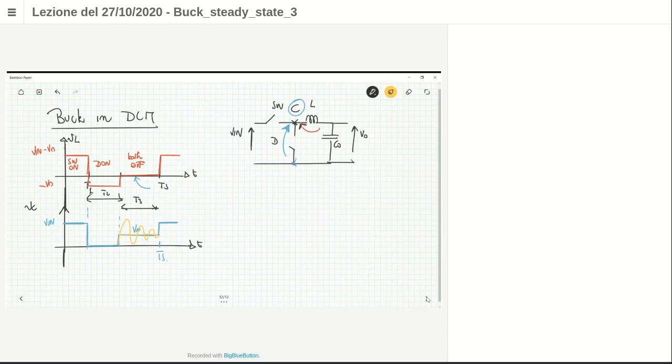For example, I just discussed with you the fact that inductors have a parasitic capacitance placed in parallel, which is due to the terminal capacitances, so the capacitance of the terminal leads, and the capacitance of the loops of conducting material that are adjacent to one another. So you have a certain C terminal capacitance. Also, the diode which is open has capacitance across it, which is the depletion capacitance of the diode, and also the switch has capacitance across it when it is open.